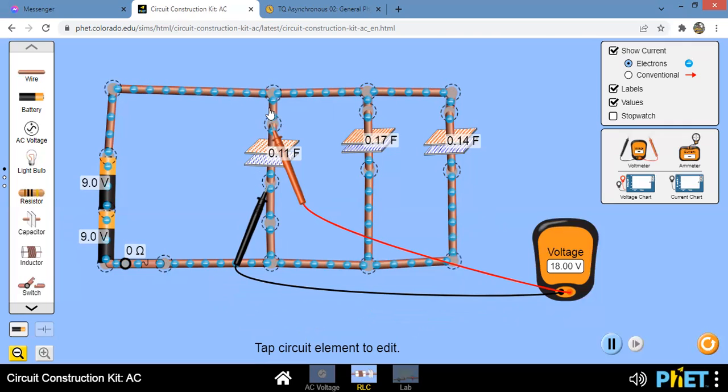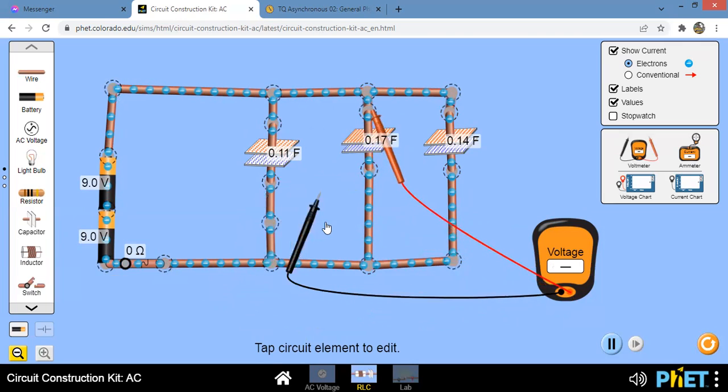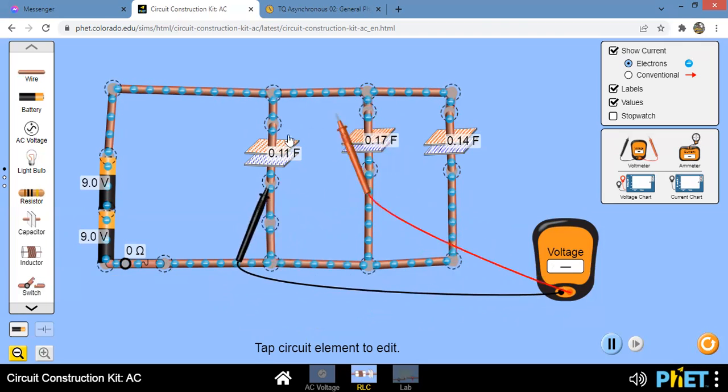So again, if you want to get the charge here, you can have the amount of the capacitance, 0.11, and multiply it by the reading of the voltmeter. So in each of these capacitances, you can get your voltmeter to measure the voltage. All that you have to do is to simply transfer this prong or this terminal, or lead, to the ends of your capacitor. So that's how the voltmeter works.